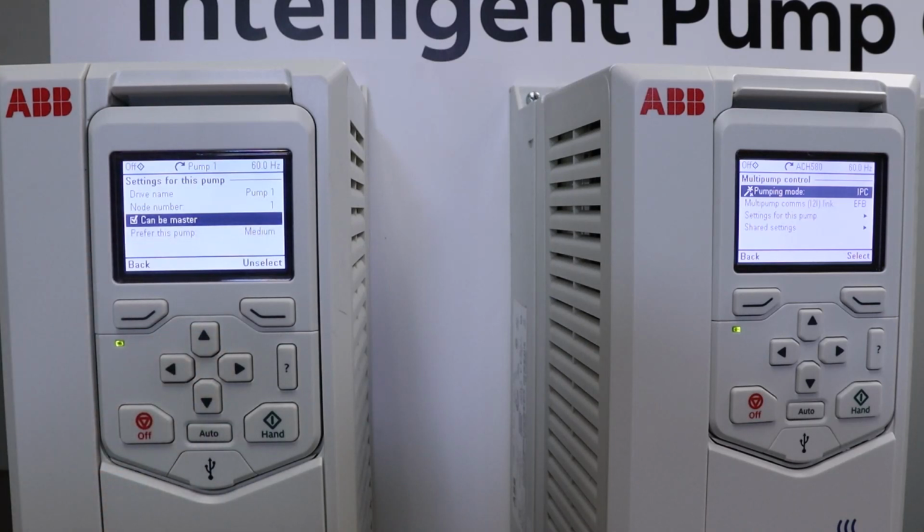And with our master drive system, we're going to select all the pumps to be eligible to be master drives, so if one drive or pump goes down, the other drives can take up the master position. Preferred pump. For preferred pump, we have several options. High, run as much as possible. If you have some higher efficiency pumps, you can set the preferred pump to high on those higher efficiency pumps, so they're used more often, saving you money. Medium. In this case here, all of our pumps are going to have the same efficiency levels, so we'll have them set to medium. And then low, it would be pumps that you'd have for some reason that you only want to run at the end and as little as possible. So that would be the low setting. So I'm going to save it for medium.